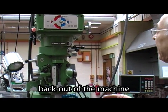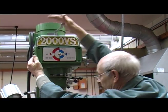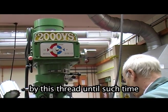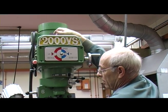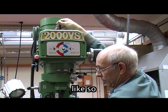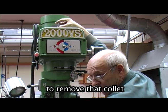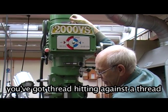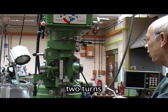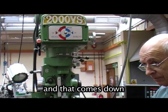When taking the cutter back out of the machine, it is critical you do not undo the collet by the thread until such time as the thread becomes loose, like so. Because now there's nothing holding that collet in. When you bash down to remove that collet, you've got a thread which is against the thread. It's only necessary to loosen probably 2 turns, tap on the top, and that comes off.